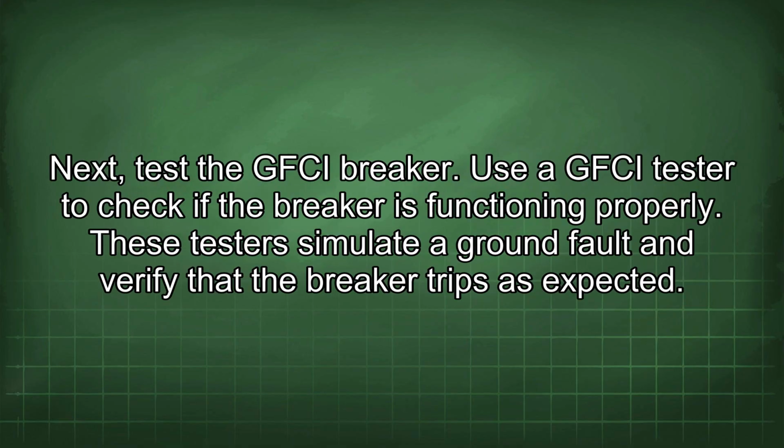Next, test the GFCI breaker. Use a GFCI tester to check if the breaker is functioning properly. These testers simulate a ground fault and verify that the breaker trips as expected.